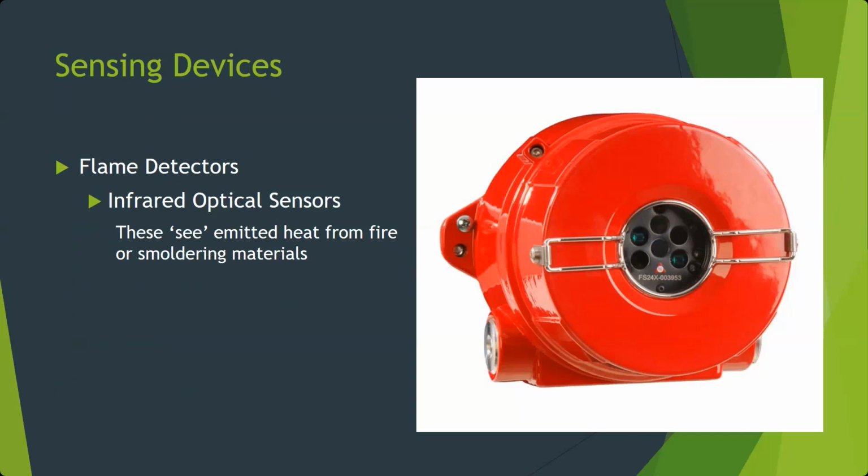So these can monitor one area. One of the first uses was in military and helicopter applications, where they would be pointed at the engine gearbox and the rotor gearbox. If the rotor gearbox started to overheat because of something going wrong in it, they would get an advance warning before the rotor gearbox would actually shell out and you'd have to do an autorotation, hopefully. If it shelled out so bad that it jammed the rotor, you were pretty much out of luck at that point. So hopefully they see that before.